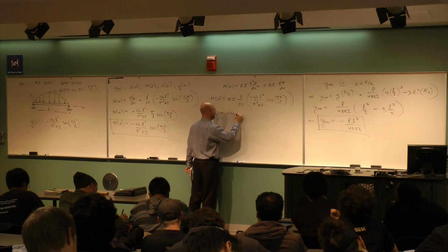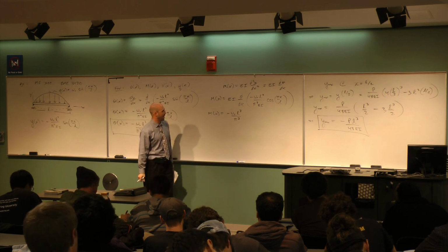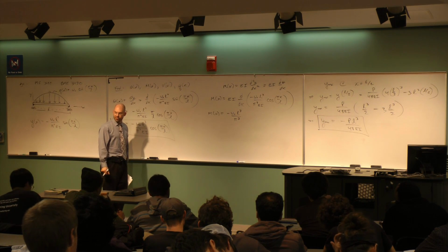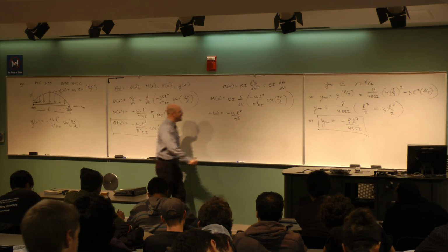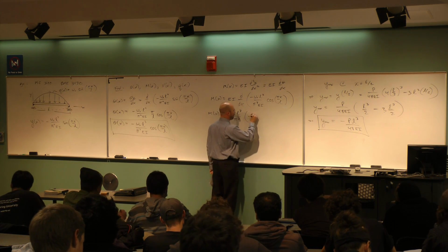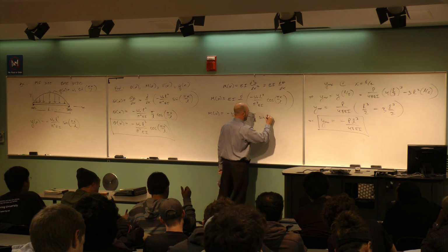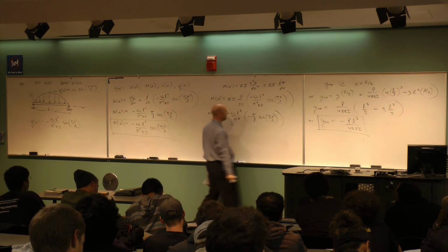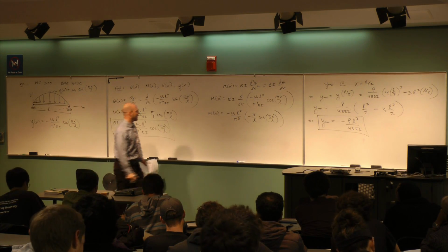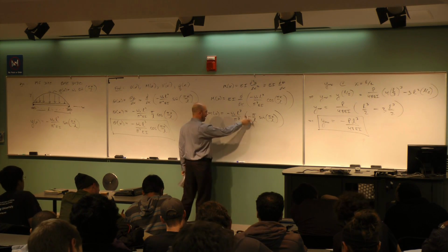Minus w naught L cubed over pi cubed. Right? I canceled out the EI. Now I've got the derivative of the cosine pi x over L, which gives me what? Negative. And the omega comes out. What's the omega? Minus pi over L out front, times the sine pi x divided by L. Does that look right? Interesting, I got 2 negatives there, which gives me a what? Positive. What happens to the pi and the L?